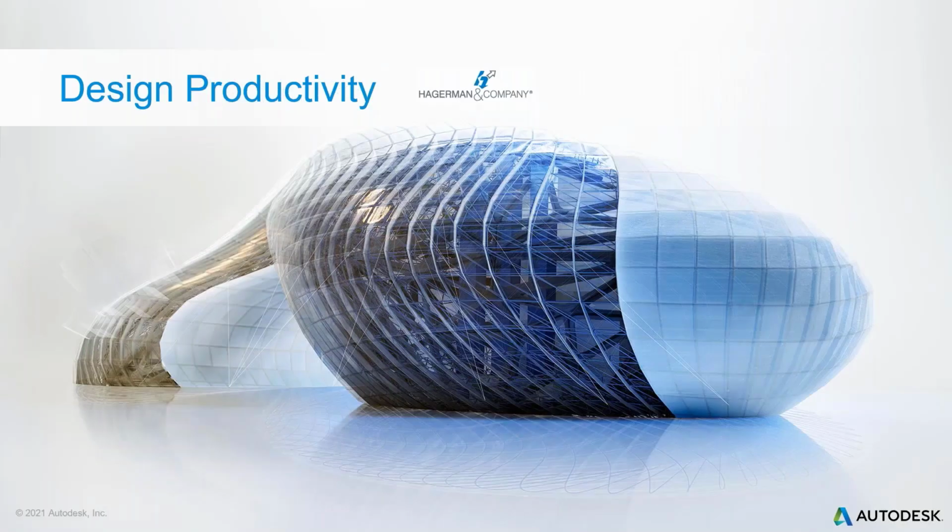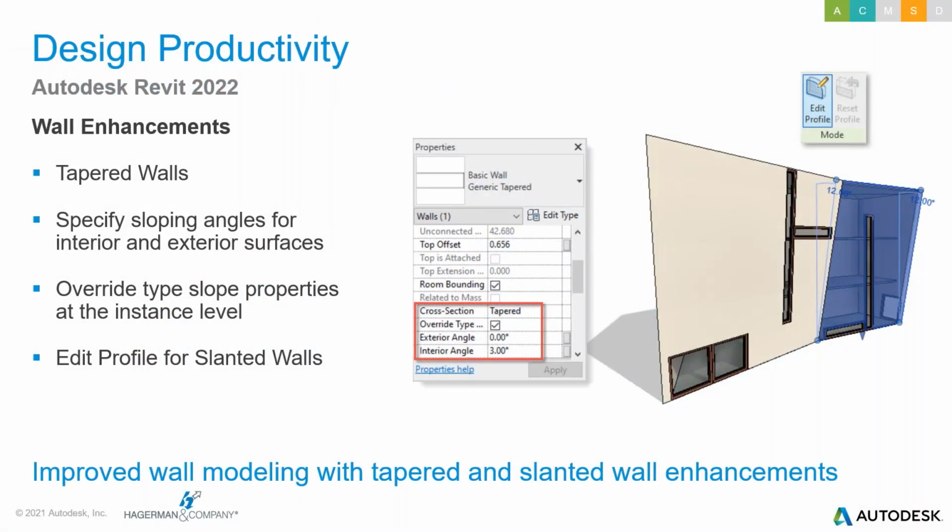So let's start with design productivity. This is pretty cool. Revit 2022 introduces tapered walls. You can change any wall to a tapered representation by changing its cross-section parameter to tapered. Then you can update the sloping angles using instance overrides or the wall's temporary dimensions.